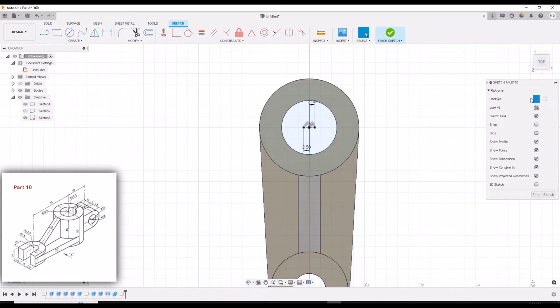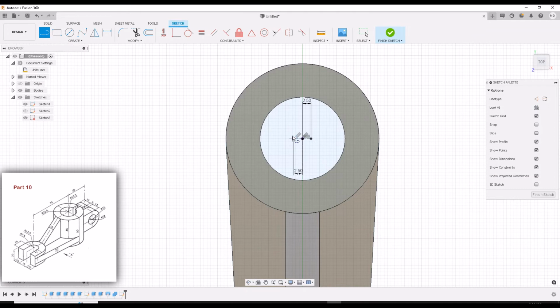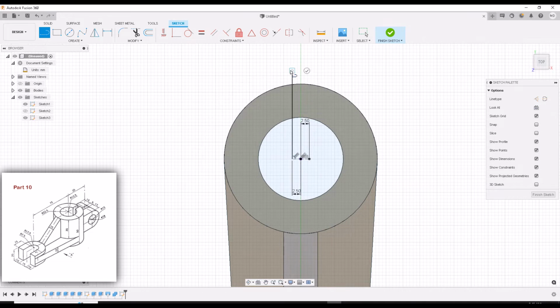All right, now let's turn off the construction line function and let's just drag these up. From these segments we just created here, you see that? So you want to go from this point and just drag it up. Drag it up through the part at 90 degrees. And you see it's trying to continue that segment. We don't really need to, but you know what? Let's try it like this.